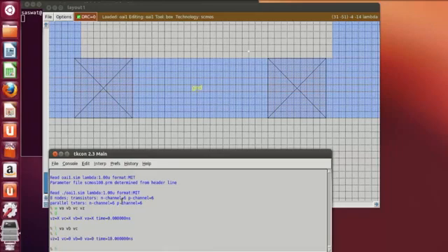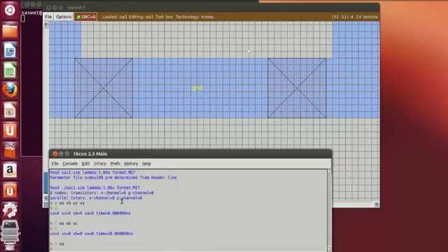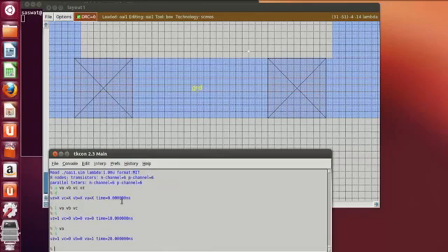Now if I give high value to VA and then press S, then the output will be 1 again, because these two are Or, that is 1. 1 and 0 is 0, so the output will be 1 again. If I give high value to VC, then I'll get VZ as 0, because these two output will be 1. This is 1, then the AND will be 1. See, the finally obtained output is 0.